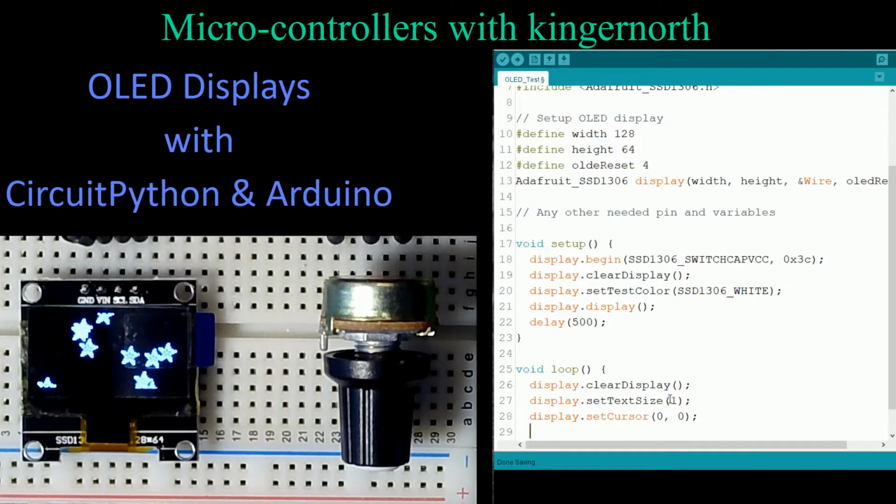And then very simply, just like we do when we do the serial monitor, we're going to put in here display dot, and these print commands work identical to they do in everything else. So we're going to go ahead and say, hey, display print. We're going to put in here, let's do this in quotes, "Welcome to the show." I'm not sure if that's going to fit in there. We're going to find out when we download that. And we're going to put that in there.